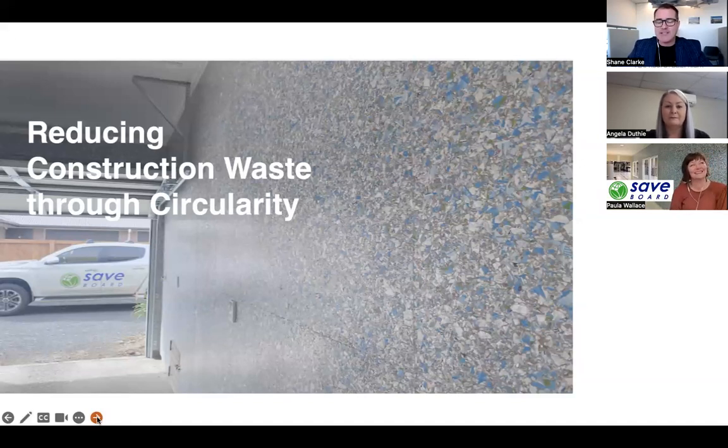There's another theme coming through. I don't know if we want to dive into this one. It's about the vapor permeability or the breathability of it. Yes. So we've got data available to share, a WUFI analysis on generic buildups. Clearly, they're all design specific and according to the zone. But zones 1 to 3 go confidently without mechanical ventilation on a standard traditional buildup.